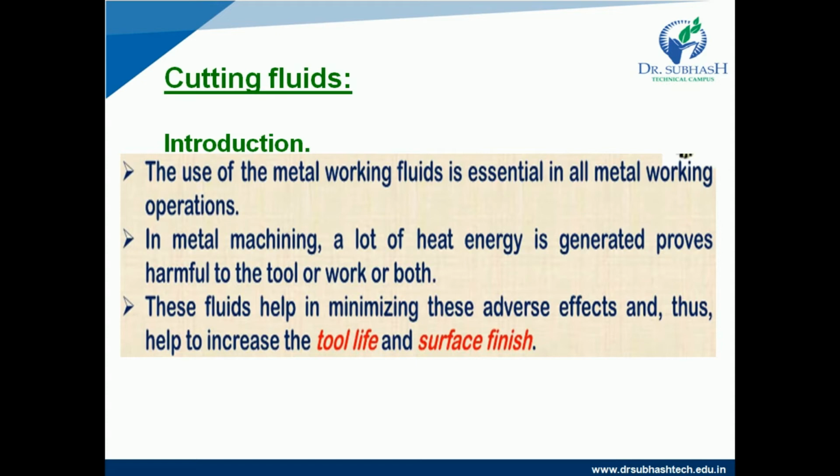As we discussed earlier, tool life is inversely related to the cutting speed. If we are increasing the speed, then definitely heat will increase. So heat will increase, then tool life will decrease, right? So this type of fluid can help in minimizing the adverse effect of the heat.